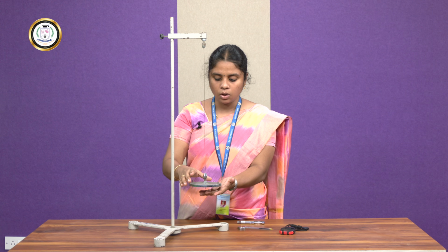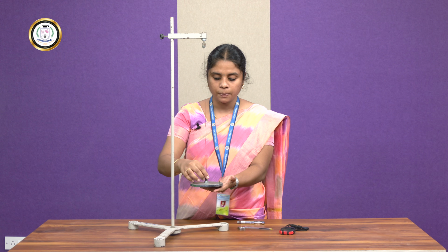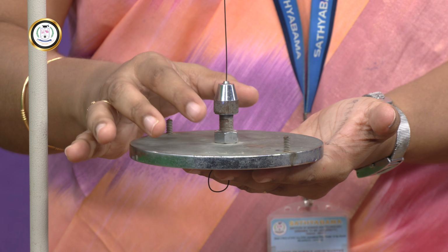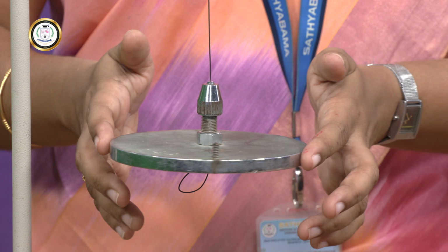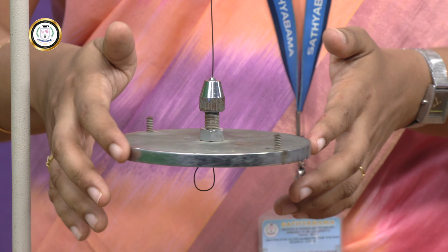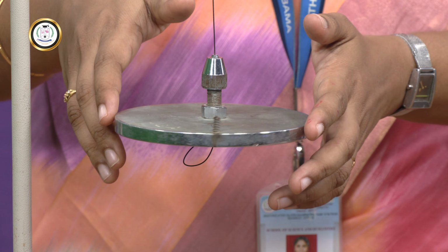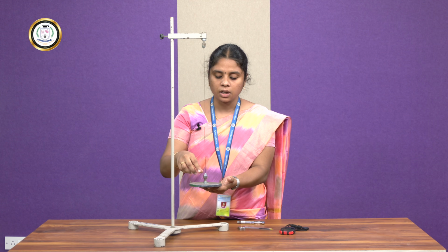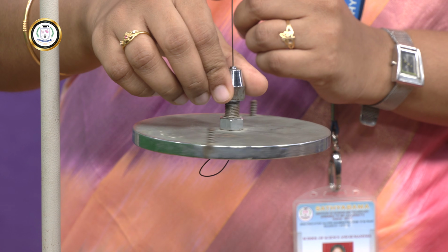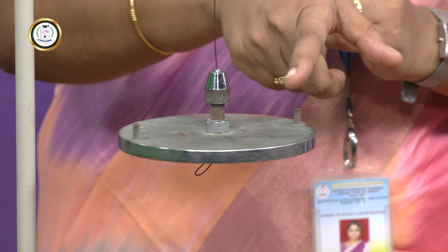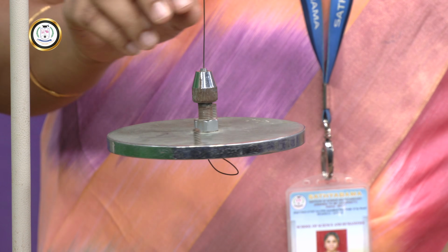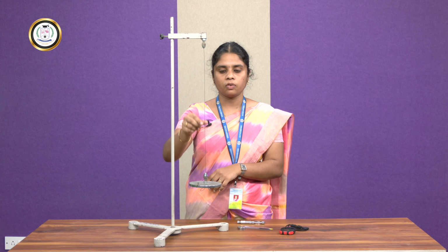So, how to measure a torsional oscillation? Initially, hold the circular disc in this position. You are going to apply a couple, and a couple is nothing but two equal and opposite forces. You can apply the couple this way, applying a force in both the left-hand and right-hand directions, or else hold the circular disc in this position and give a small amount of force by holding the screw, on both the left-hand side and right-hand side. Now the pendulum starts to produce a torsional oscillation due to the twisting of this wire.